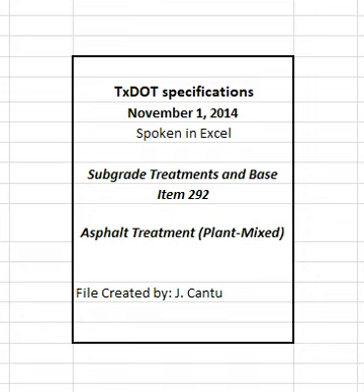2.4 TAC code. Unless otherwise shown on the plans or as approved, furnish CSS1H, SS1H, or a PG binder with a minimum high temperature grade of PG 58 for TAC code binder in accordance with item 300, asphalts, oils, and emulsions. Do not dilute emulsified asphalts at the terminal, in the field, or at any other location before use.